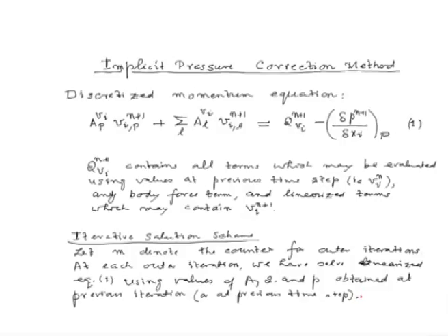we would solve for an intermediate velocity field, since on the right hand side we are using the terms which are based on the previous iteration, and if we substitute those in our equation, they will not satisfy the momentum equation 1, and the velocity field which we obtain thereby will not satisfy the continuity equation either. Thus, we do not try to immediately obtain an estimate of the velocity field at the current iteration which would satisfy continuity.